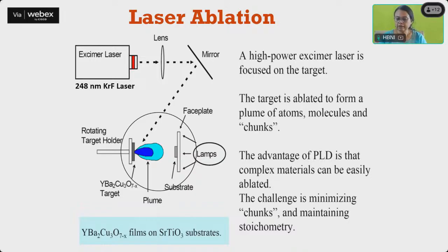There is a question: what are the applications of sputtering? All the applications are in thin film deposition, and sputtering is used for the deposition of oxides and nitrides. So if you want to deposit an oxide film like SiO2, alumina, or a similar thing, or a nitride like tungsten nitride, tungsten carbide, silicon carbide, this kind of film you cannot deposit by thermal evaporation. You have to use sputtering.